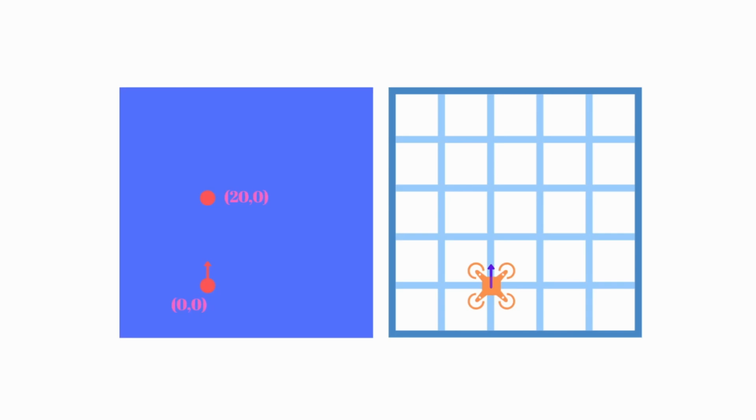In this chapter, we are going to look at how we can map our drone. Now, this is also known as odometry. The idea here is that we are going to use the velocity information to find the distance, and we will also use the angular speed to find how much angle the robot has or where it is headed. Based on this information, we are going to get the X and Y coordinates. So we will take the distance and the angle and convert it into Cartesian coordinates so we can plot it in a graph. Let's have a look at the explanation of this before we actually go into implementing it.